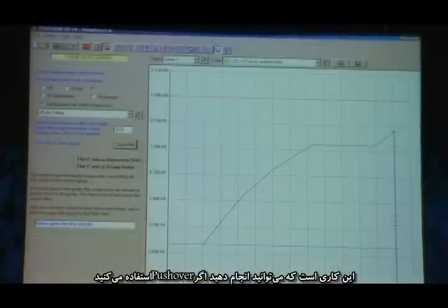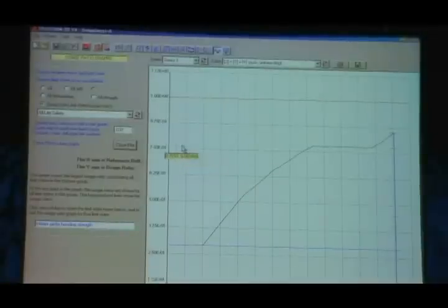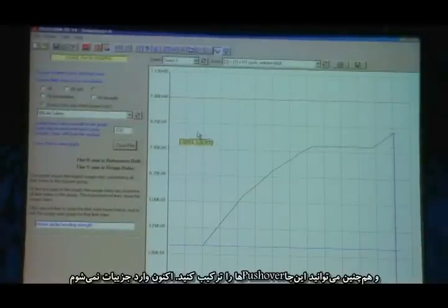One of the things you may notice is if the dynamic analysis, these top two were reversed, but this is not necessarily a response spectrum that corresponds to those dynamic analyses. So this is what you would do if you were using pushover, and you can also combine pushover here if you want to as well. I'm not going to go into the details on that.